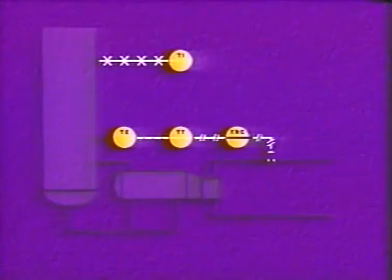These symbols show a temperature indicator, an industrial thermometer connected to an indicating gauge. The gauge is connected to the thermometer by capillary tubing. In other words, a liquid or gas expands or contracts inside the tubing, and this indicates temperature. The capillary tubing is shown by a line crossed with a series of X's.